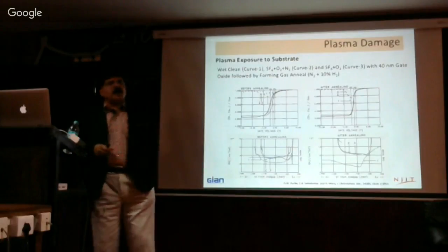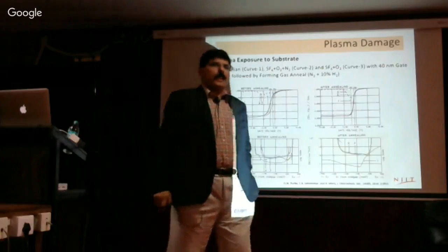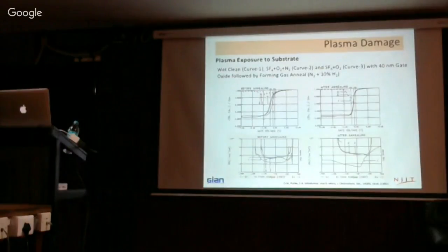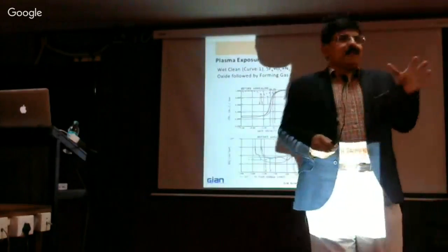What I'm saying is, if you have a backside contact sitting on the chuck by gravity with your probe on top, you have to have a better contact. If you don't have vacuum, use some silver paint to make good contact with the substrate. So these are small experimental things.